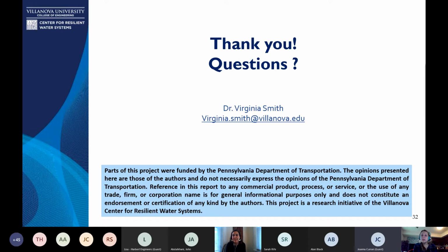All right, looks like this is the last question so far, but feel free to keep typing in and asking questions. It says, what is the limiting factor for a GSI's lifetime? Contamination, silting up, etc. It really depends on the GSI and the environment that it's draining. The most common reported problems from the publications appear to be around sedimentation, debris, clogging, and erosion.